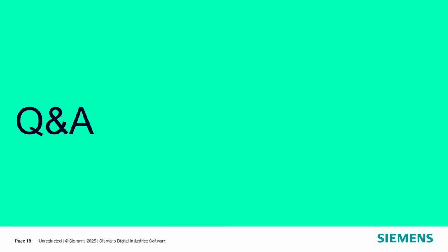Joe again: most efficient way to get objects in CAD and CAE by name. If you have named the object, you can just do a list comprehension on the object.name property. Compare those, and that should give you your name. Be careful there that if you have things with multiple names, list comprehension will give you all of them back. If you then take the first one, that might not always be what you want.